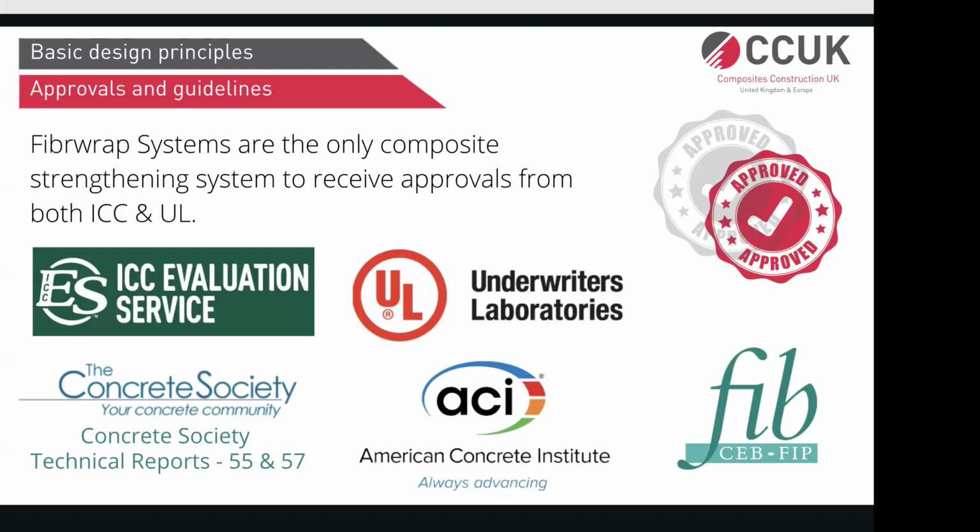Now, if you note, I'm saying they're design guidelines. They are not design codes. There are different countries which have their own design guidelines. For example, Canada has its own guideline, Switzerland has its own guidelines and all. So at the end of the day, there is not a set code to design FRP, for example, a Eurocode or a BS code or something like that. And for that reason, you don't see too many engineers designing FRP as a common material, because you don't have a set parameter based on which it can be designed anywhere in the world.